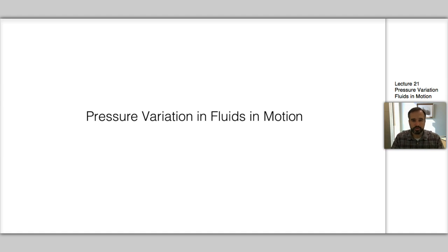However, before we get into the control volume analysis of conservation of momentum, we need to consider all the forces that come into play when we're going to build that balance. And the first one I'd like to talk about, because we already are familiar with pressure, is pressure variation in fluids in motion. Recall from your hydrostatics class that pressure is very important. It's equal to the specific weight of the fluid times the amount of fluid above it. So it's basically the weight of the fluid above the point that you're looking at. And it gives us a force when we multiply it by the area. And so we need to look at how that's going to ultimately be incorporated into our momentum equation.